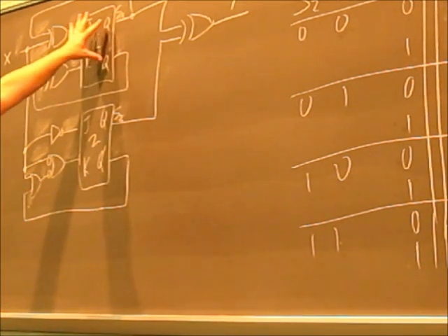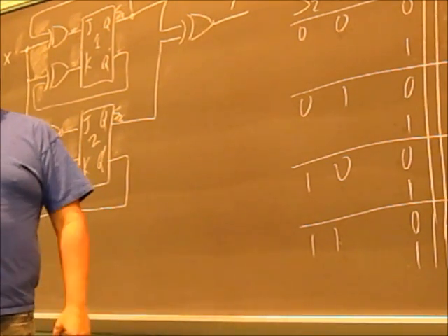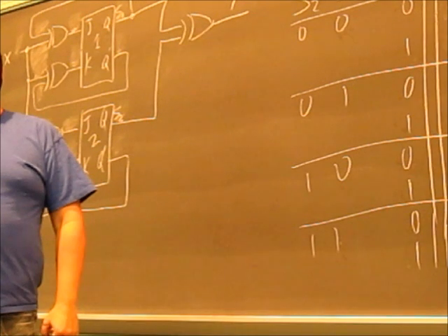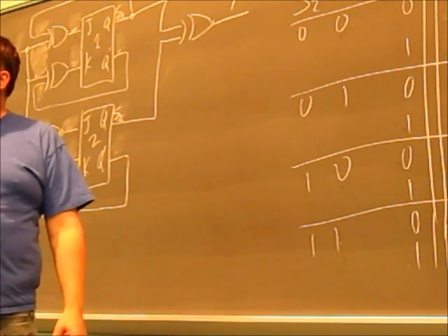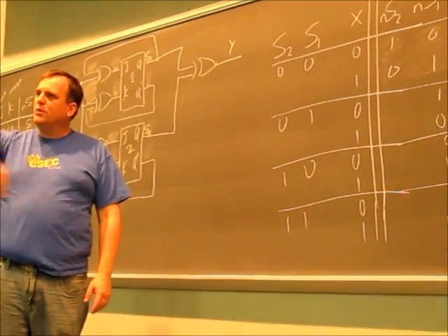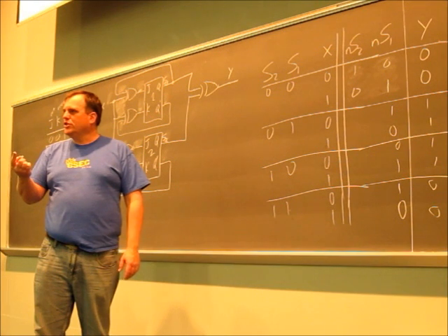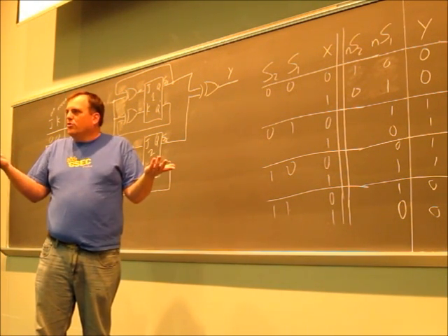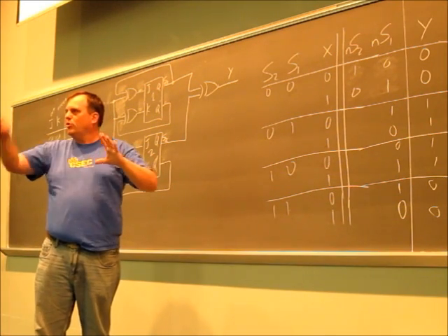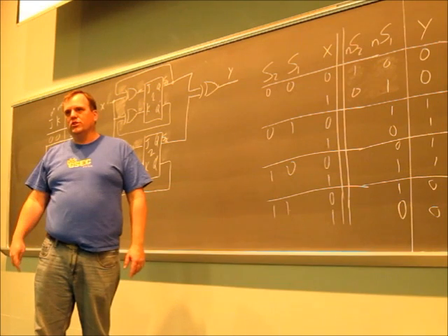The reason why we do this and I use this is because flip-flops, remember, always have both states. They always, always, always have them. That's how we built them. Remember we took the two NOR gates and fed them back into each other? And the output of one NOR gate gave us Q and the output of the other gave us Q prime? That's how we built them. We took two NOR gates and just hooked them up circular style, and they feed their signal back into each other.